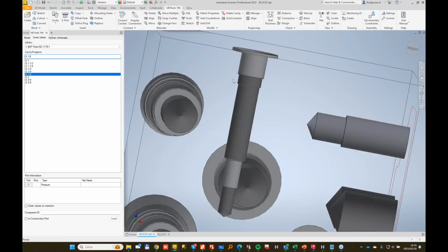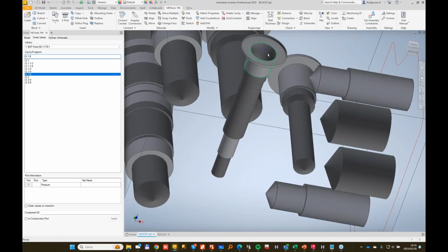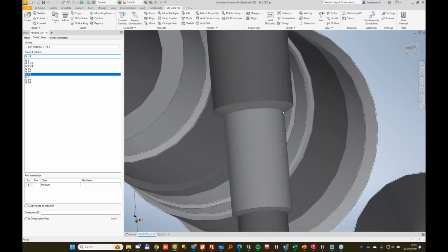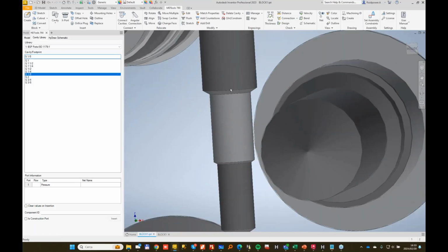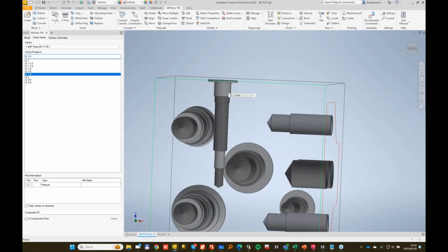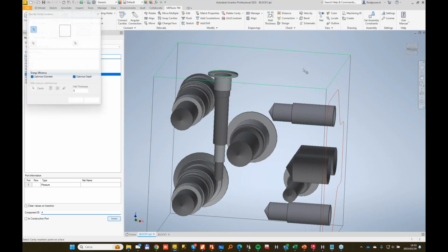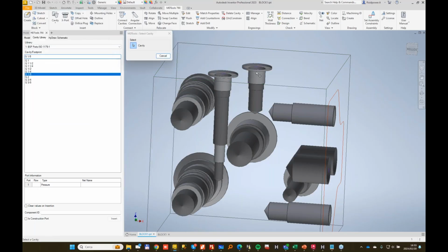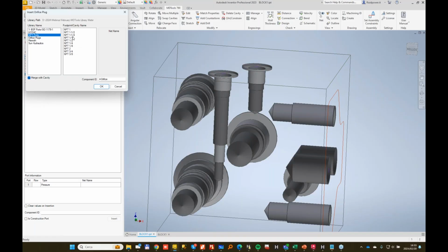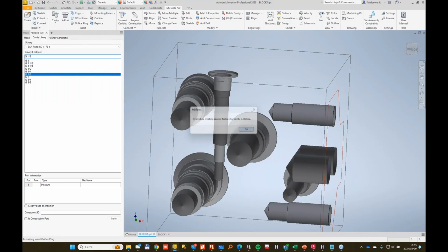This may not always be so precise, and this is something that I notice in the machining drawing, because since the drill is added at the end of the chamfer, then the dimension is not always precise. There are also some decimal places which I don't like. So sometimes I need to manually fix. But recently I discovered another problem with the NPT ports. So if you try with a small diameter to add an NPT 1/16, which is pretty common as an orifice, then there will be a cavity failure.